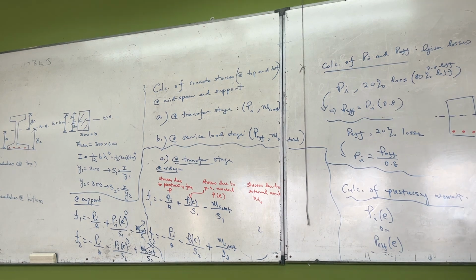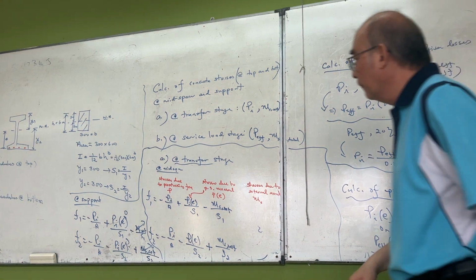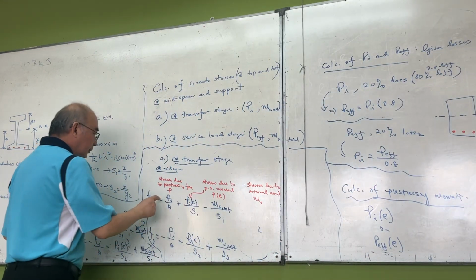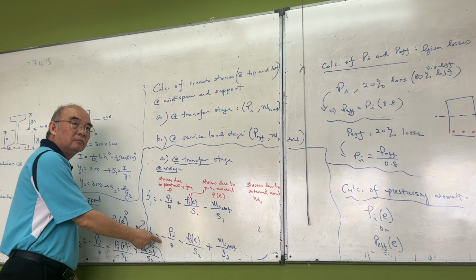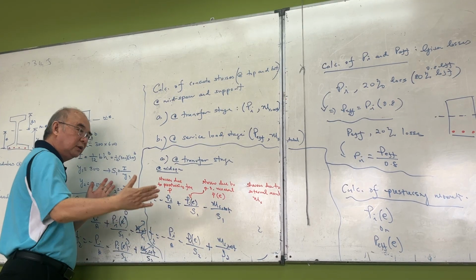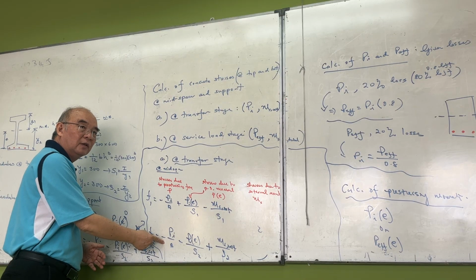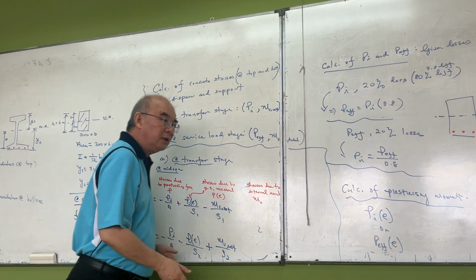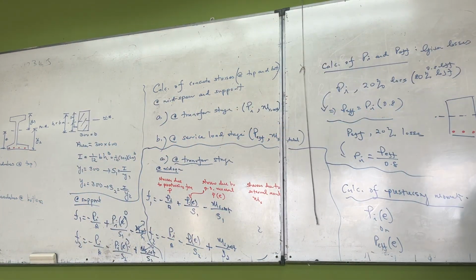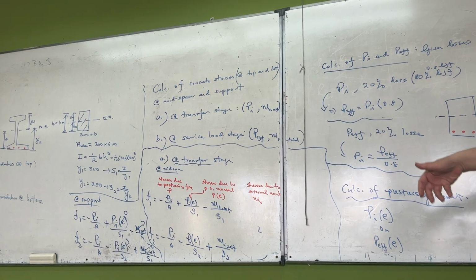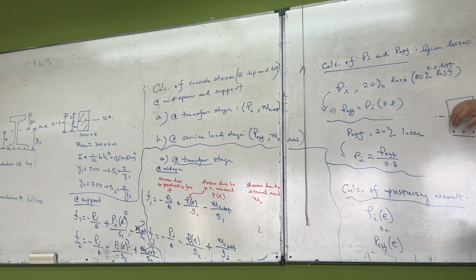Now the sign convention. Compressive stress, negative, negative. Due to pre-stressing force, whether top or bottom is compressive stress, negative, negative. Then the pre-stressing moment, because the force is like that, the pre-stressing moment is like this: bottom compression, top tension.